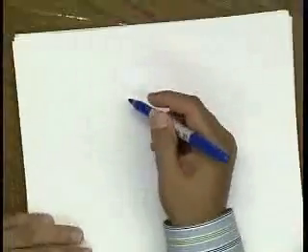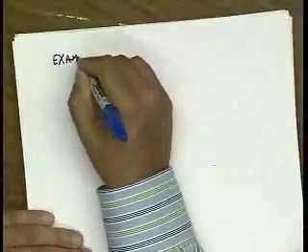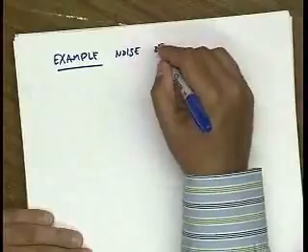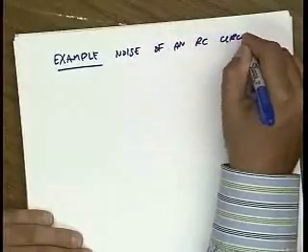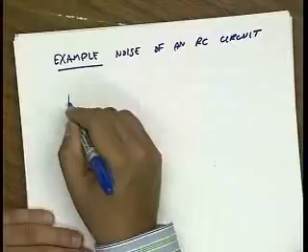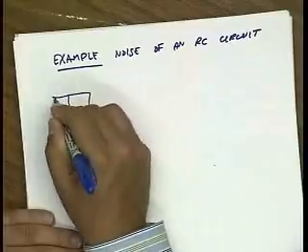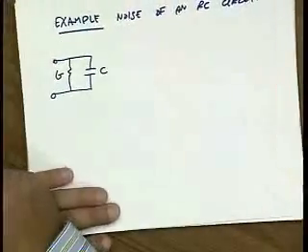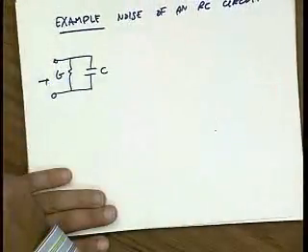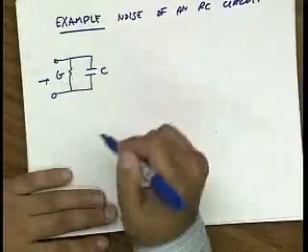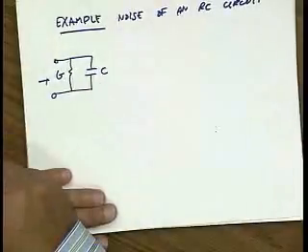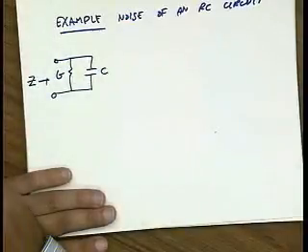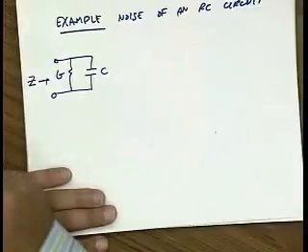All right, so let's do another example. And this is one of those really important examples that will stay with you. Let's look at the noise of an RC circuit. Okay, so an RC circuit looks like that. And we want to find the equivalent noise looking into this terminal here, right? So this is going to be our black box. Well, according to what we just learned, all we have to do is calculate the impedance and take its real part and associate noise with that real part.